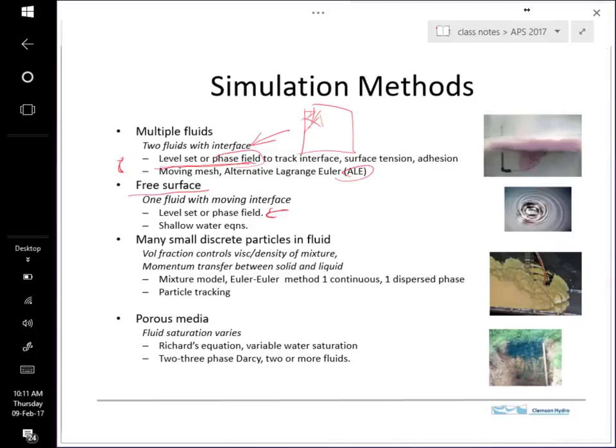You're making it into, if you wanted to analyze the flow in the oceans, for example, you would think of it as really a 3D problem, but with this approach, you're averaging over the depth and you reduce it to just a 2D problem, okay? So it simplifies it down, it makes it a lot more tractable. And those equations are called the shallow water equations. So they would be part of this free surface analysis.